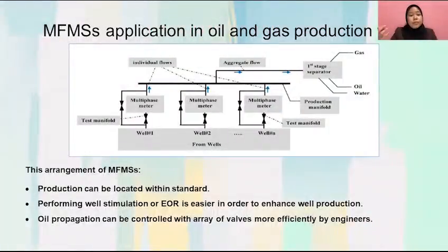As you can see from the figure, this is the example of application of MFM in offshore production and consisting of several nearby wells. The flow data gathered along a pipeline section of a given well can help in identifying how well this well contribute to aggregate flow and hence may help in locating production anomaly such as water or gas breakthrough in the actual well.